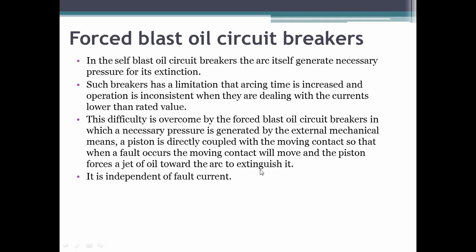So this difficulty is overcome by the force blast circuit breakers in which the necessary pressure is generated by external mechanical means. Means a piston is directly coupled with the moving contact so that when a fault occurs, the moving contact will move and the piston forces a jet of oil towards the arc to extinguish it. Okay, means what is happening there?